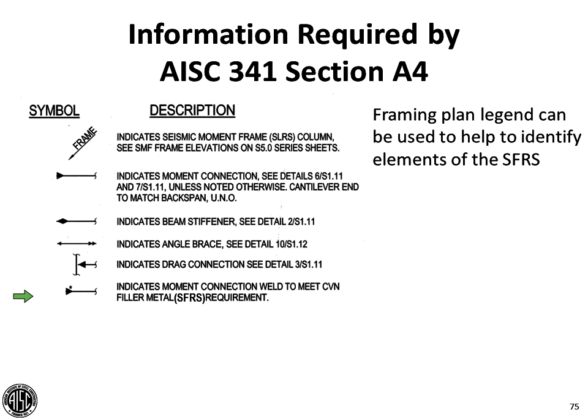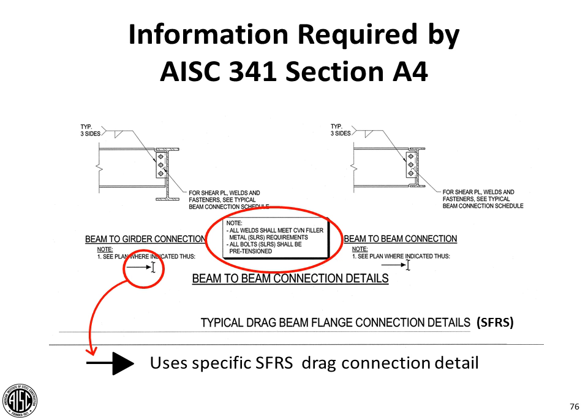I just condensed it to show the ones that are related to the seismic force resisting system. So here's the one, for example, that looks like a regular moment connection, but also needs to meet the Charpy V-notch filler requirements for the seismic force resisting system. And then an example of what that specific SFRS drag connection might look like.